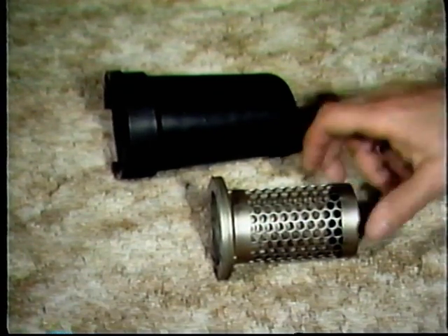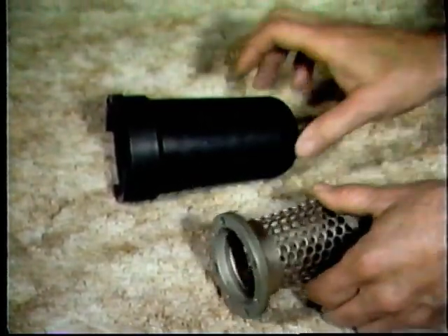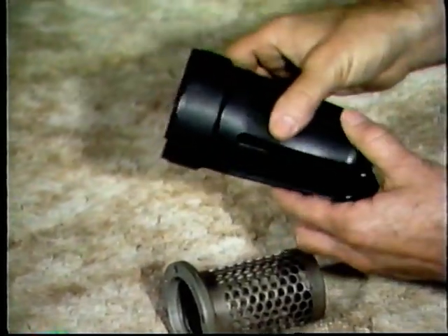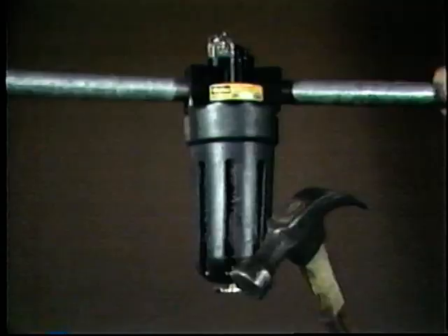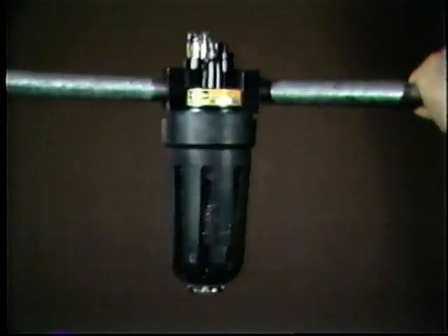Although metal bowls will resist the action of most solvents, strong acids or bases, even salt-laden atmospheres, can damage them severely. It is also common practice to protect polycarbonate bowls from mechanical damage that might be caused by a sudden blow. Two types of bowl guards you may see are this one here, which is made of metal, and this one here. It's made of polyethylene. As you can see, the guards do a very nice job of protecting the bowl from damage.